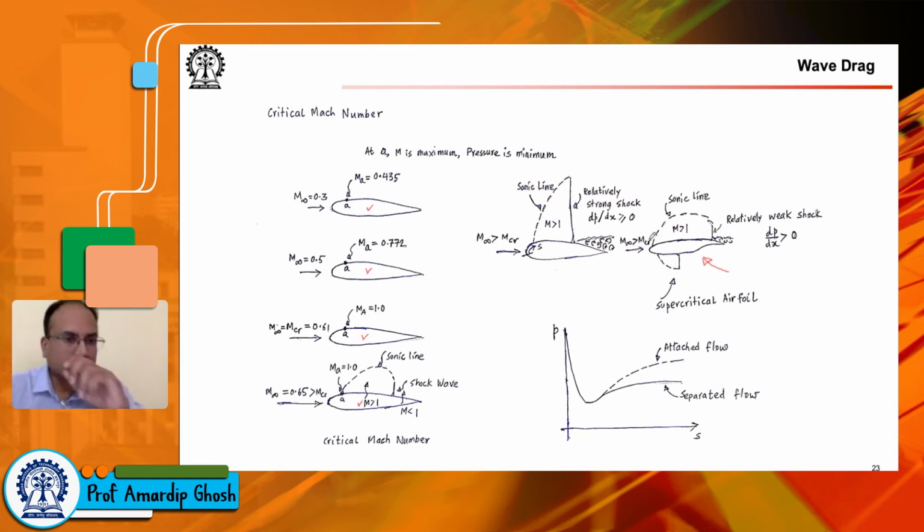So first of all, we will get into the discussion of what the critical Mach number is. Oftentimes you will see this thing called MCR, that is M with the subscript CR, or the critical Mach number. So think of an airfoil as shown here, and think of the point A, which has the special property that flow accelerates. You have a stagnation point here. Then the flow accelerates, and then at some point downstream the flow decelerates.